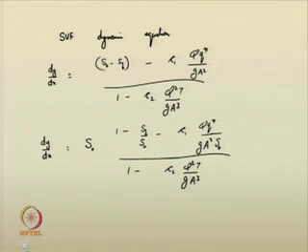So, recall the module 1 and module 2 portion. We had defined discharge with respect to conveyance factors, and we had described them. So, using the conveyance factor, Q is equal to K SF to the power of half. K is the conveyance factor, SF is the friction slope, if you remember them.